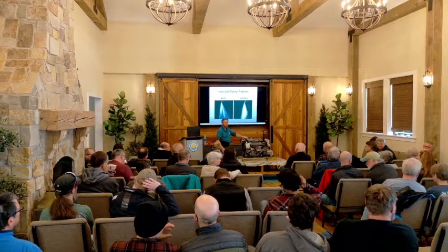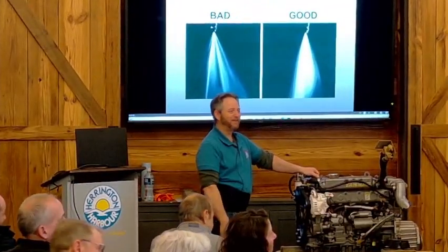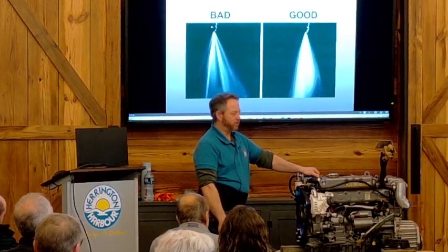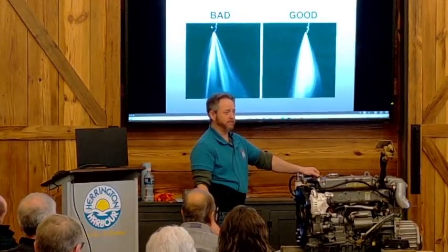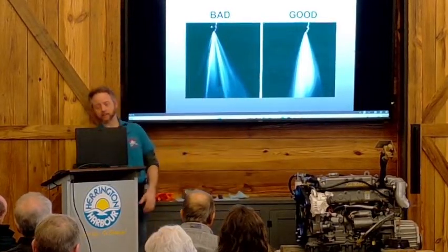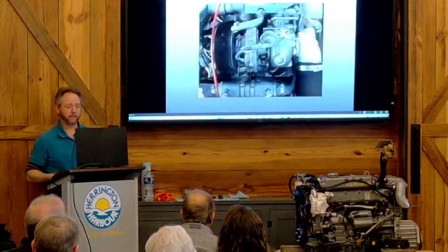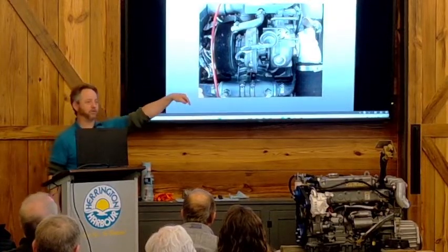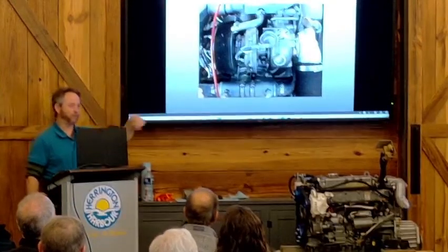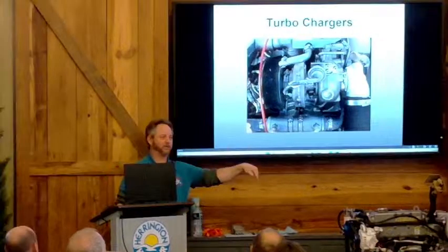If you have time to talk about the fuel filter issue. Which issue? Well, there's usually 2 fuel filters in the system. So you have a primary and you have a secondary. The Racor is considered primary. So where does the fuel start? The fuel starts at the tank. Then the first filter, primary, then that travels through to the engine, which is the second filter, secondary.